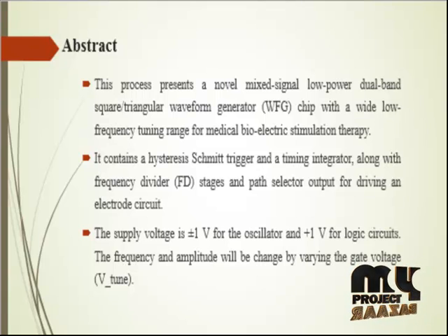This product presents a novel mixed signal low frequency dual band square and triangular waveform generator chip with a wide low frequency tuning range for medical bioelectrical stimulation. It consists of a relaxation oscillator comprising a hysteresis limit trigger and a timing integrator, along with frequency divider stages and a path selector output for driving an electrode from 16 selectable channels.